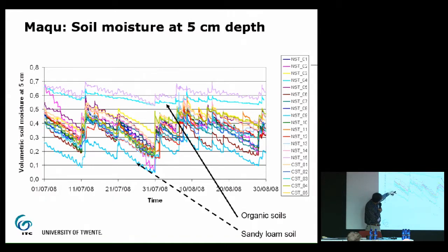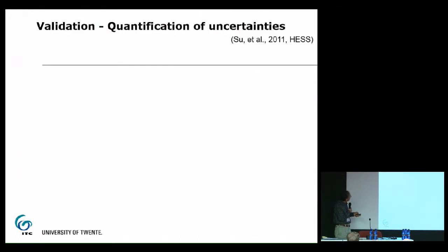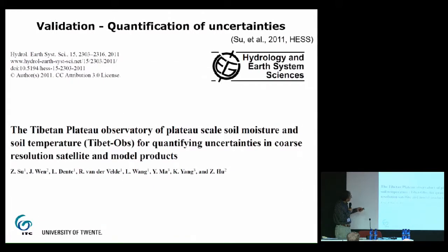And then if you look at the diurnal cycle, it tells you the kind of evaporation. And if you extract the information from this data, you should be able to model evaporation very well. And here, basically, the reduction of soil moisture due to evaporation. So this gives you actually a lot of information that you can use both in modeling and in remote sensing to see, okay, what is really measured. And that was also motivation that we put this network together so that we can always look at what's happening there. So the first thing we did was basically put up a paper describing the network.